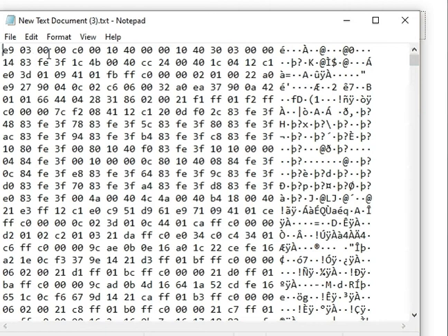And also they have various methods. The reason why we upload firmware is to check the AT commands when you are using a Wi-Fi module. That is, when you transfer data AT from the Arduino, you should get a response back to the Arduino from the Wi-Fi module unit. If AT commands are working well, then only can you proceed with a particular application, if you want to build one.